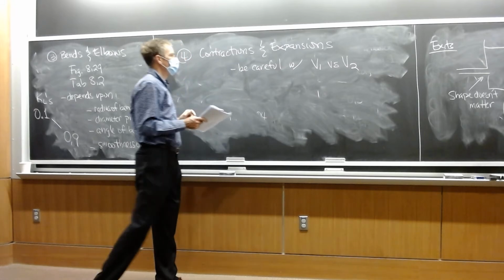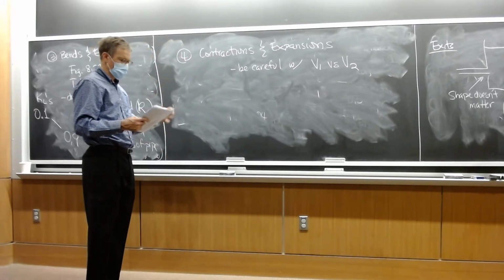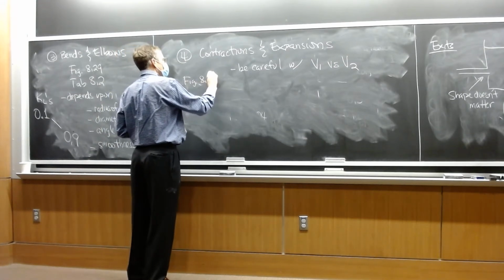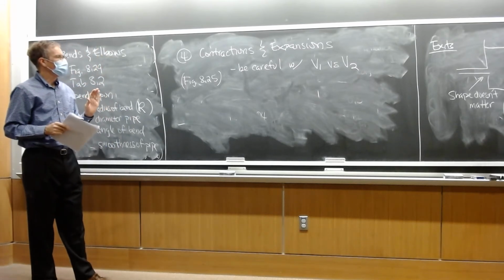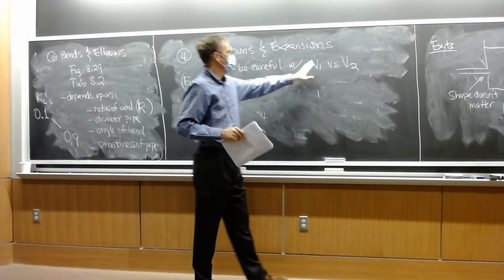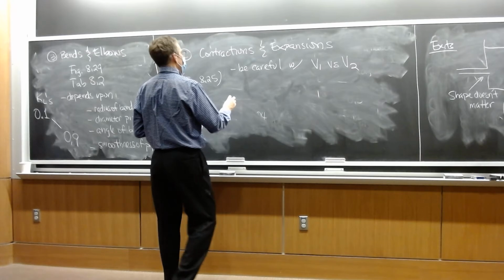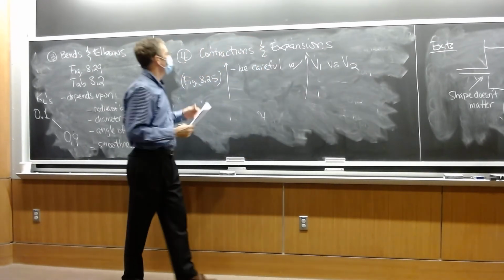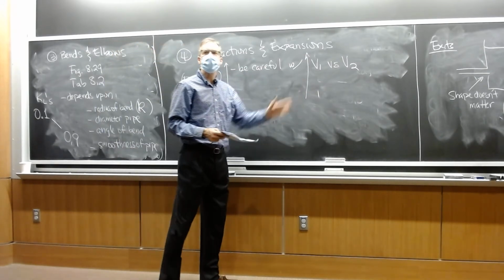But there is a figure, and they are clearly marked as to whether that K of L gets multiplied times the velocity head V1 or the velocity head V2. And you can think of contractions kind of like an entrance and expansions kind of like an exit.